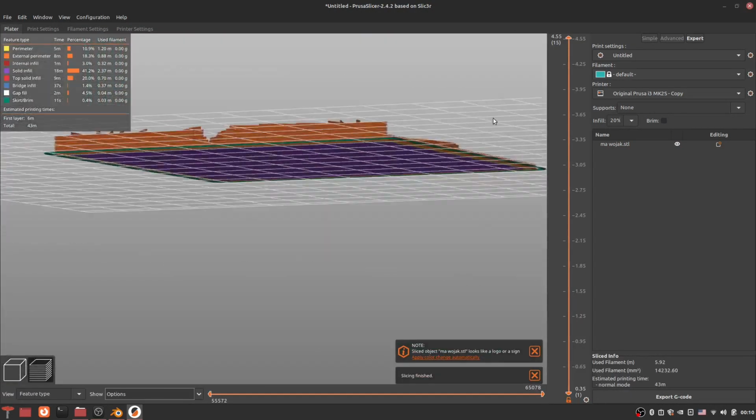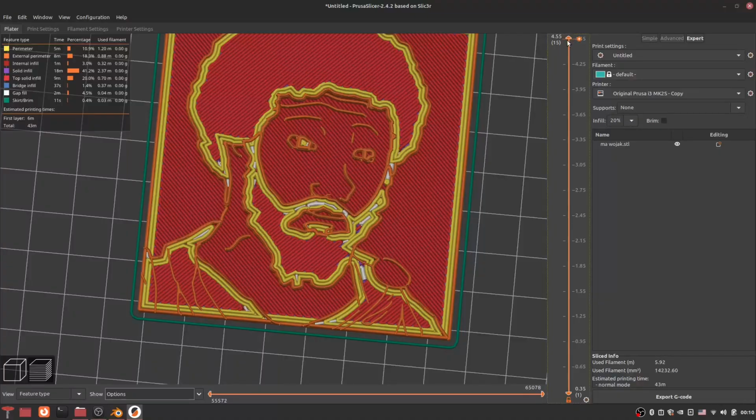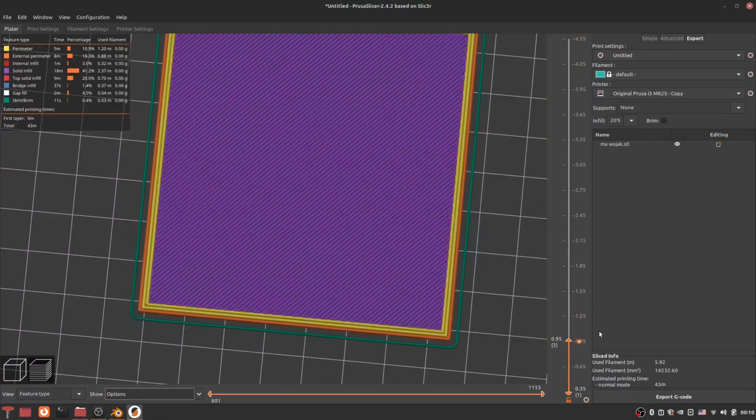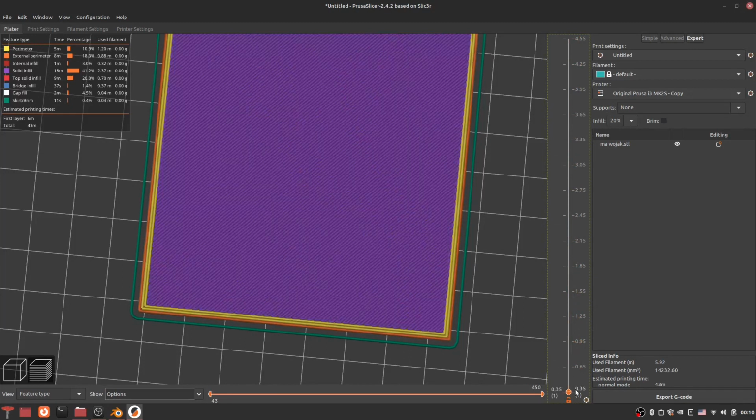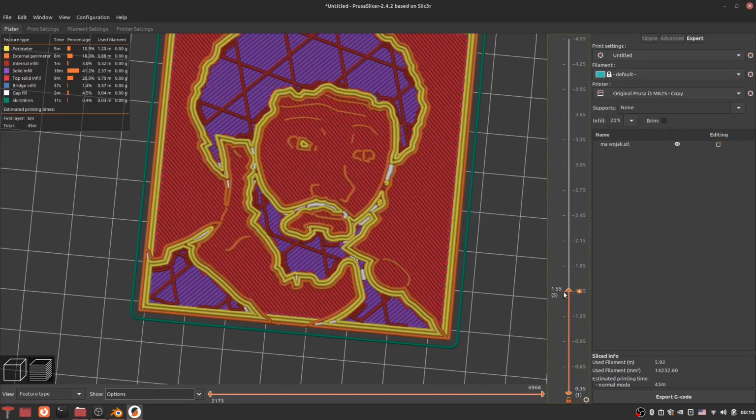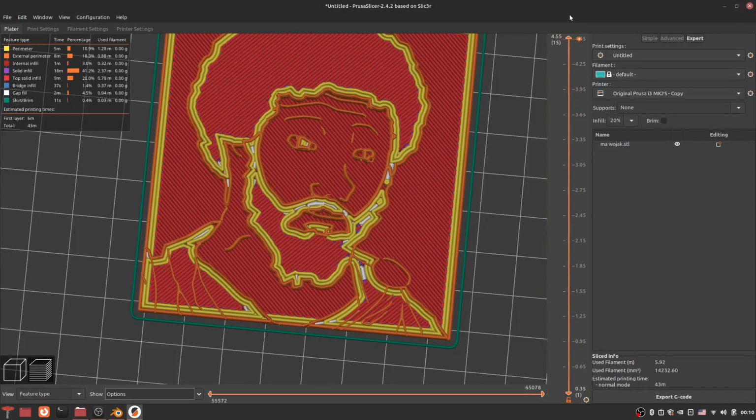And everything works, all the contours are drawn, there are no weird cavities. Use the slider on the right to travel between layers, and knowing that this process works, you can now jump between the initial picture, SVG file, model and physical print in order to achieve something cool. We'll print in the next video.